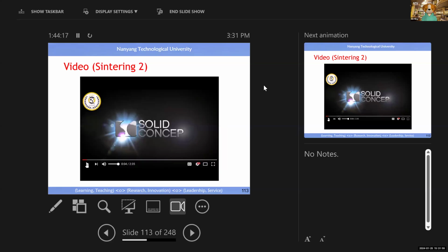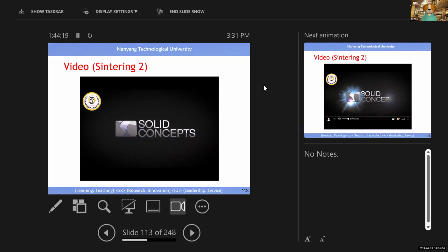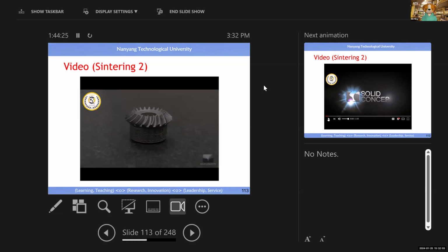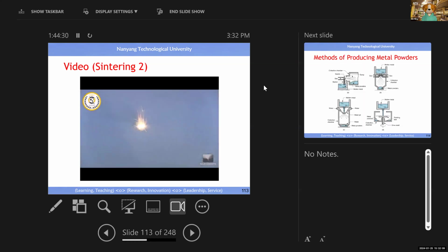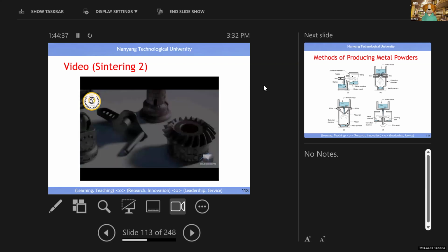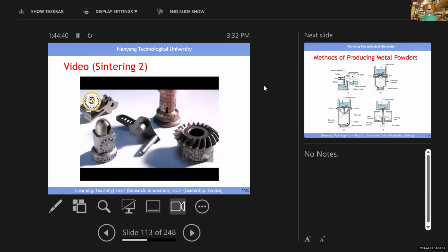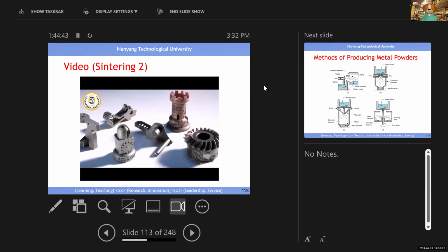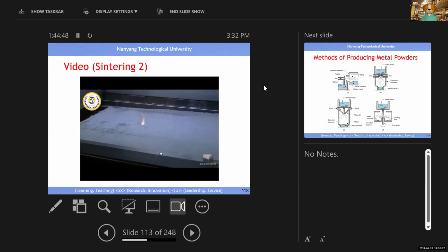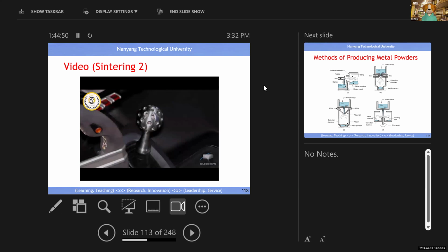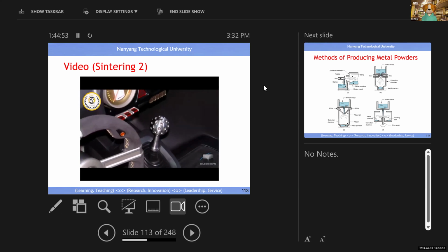Okay, so good enough. Then one more example. And this one you could use to solidify the powder layer. Direct metal laser sintering, also known as DMLS, this technology creates metal parts directly, but actually it looks like a strip. DMLS utilizes a variety of metal and alloy materials, such as stainless steel, cobalt chrome, and aluminum, to create strong, durable parts and prototypes. DMLS is an excellent choice for functional metal prototypes, high temperature applications, and end-use parts.